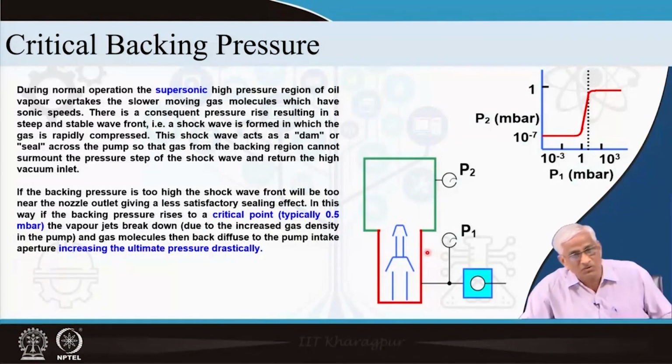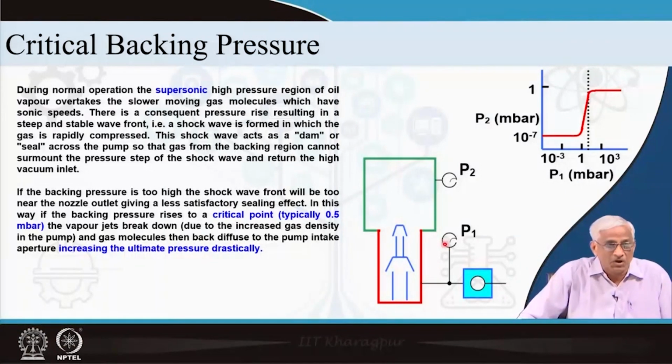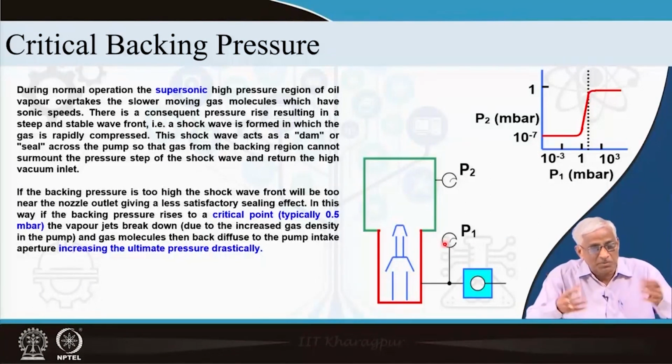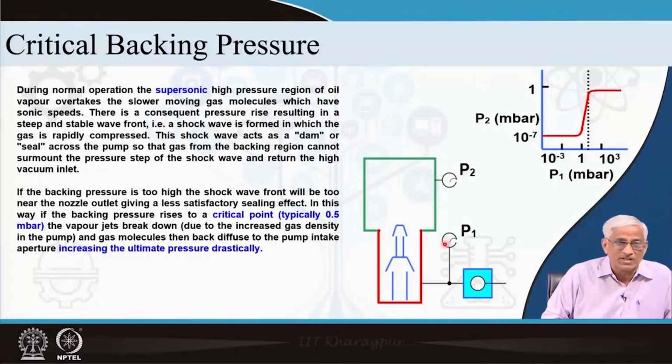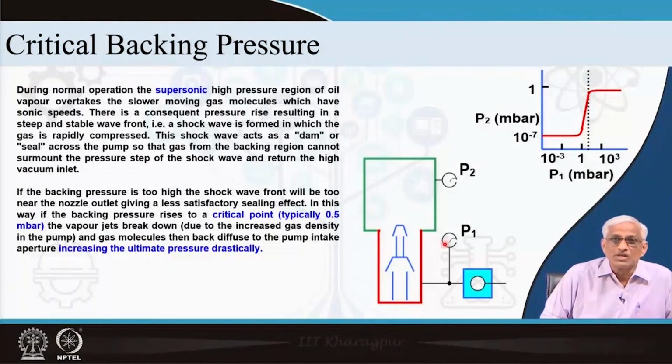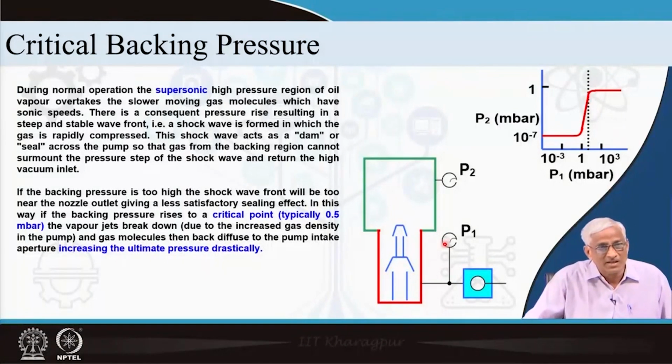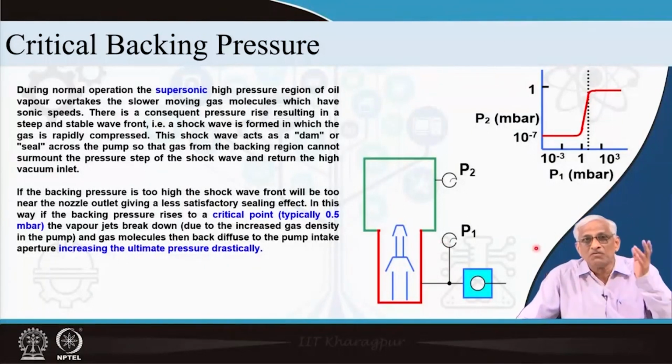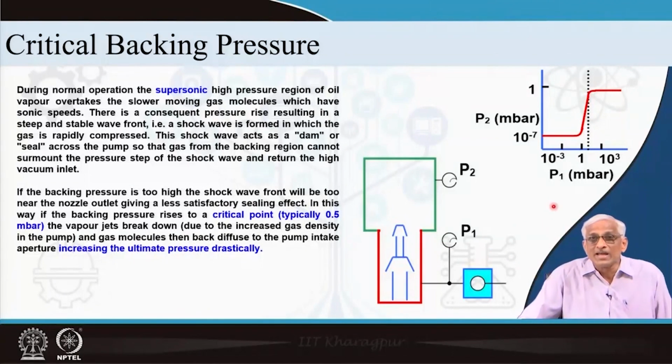Several times I have offered courses in several companies where they got into these troubles in vacuum interrupters, manufacturing, electronic industries, capacitor making, etc. They were having this type of troubles. So, we solved those troubles by properly matching the pumps, rotary, diffusion, etc. So, the criterion is you should see to it that the backing pressure never crosses the critical backing pressure even under loading conditions.